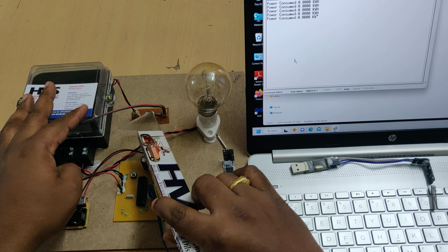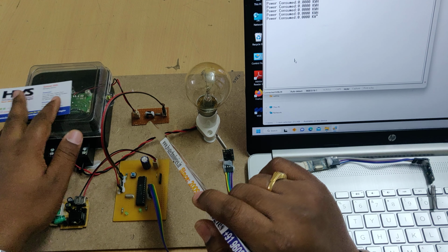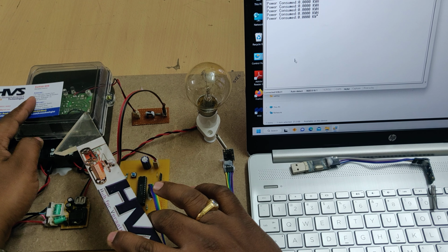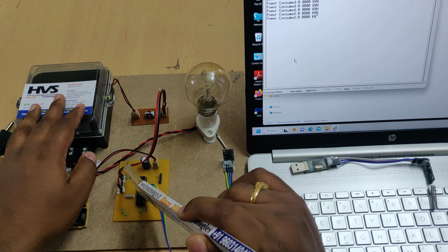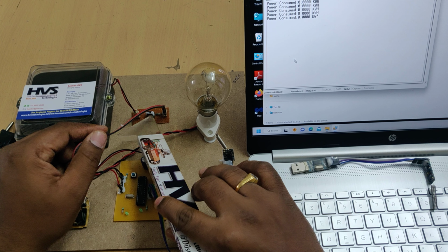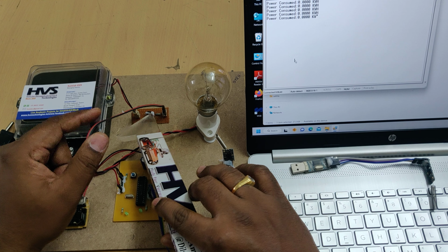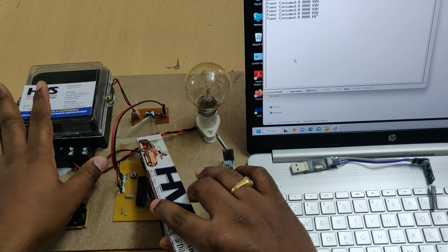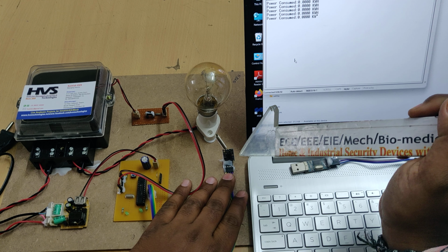This isolates the energy meter from the microcontroller. If any short circuit occurs inside the energy meter and this wire is directly connected to the microcontroller, the microcontroller may get damaged. In order to protect it, we place the optically coupled IC, the PC817. Only this IC may get damaged if any short circuit occurs, so we can protect the main motherboard along with the RF transmitter module.